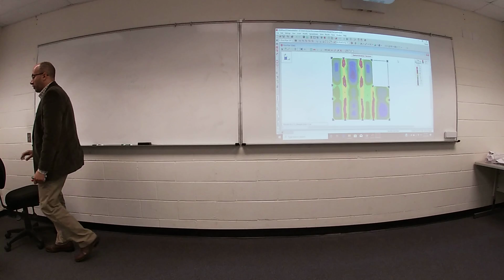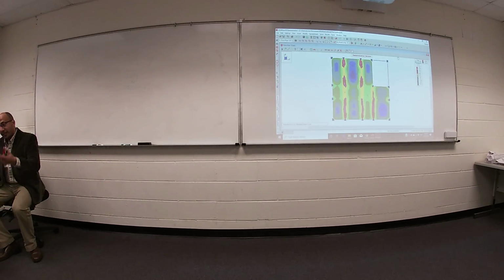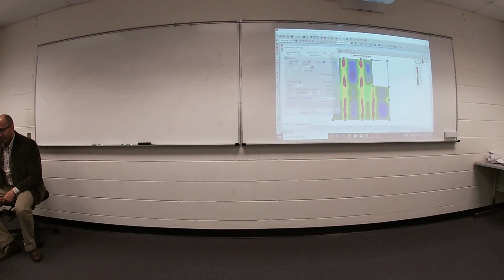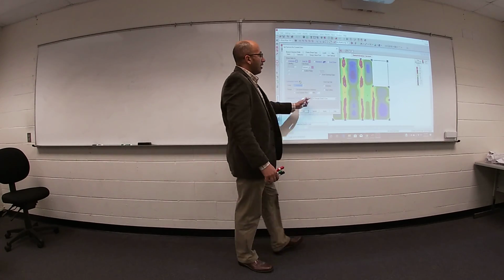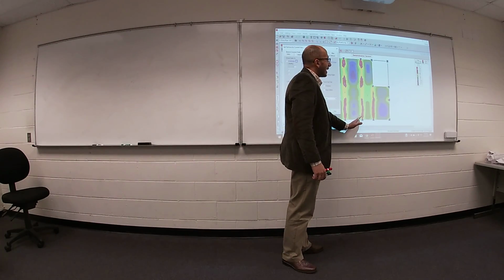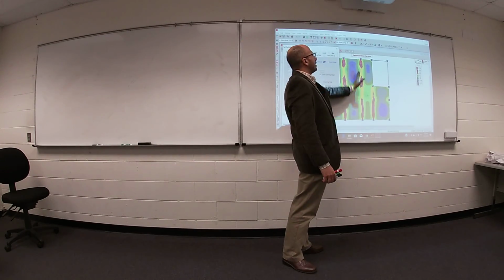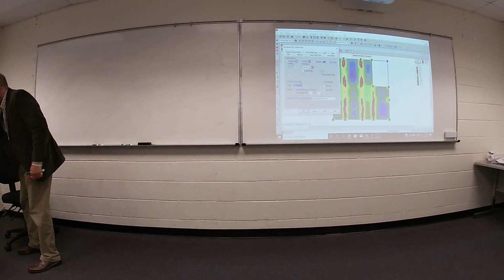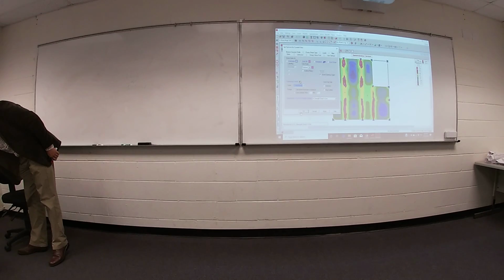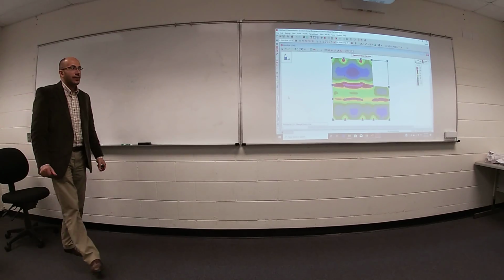If you would like to show another thing, we are looking for Mx. Mx will show you the bending moment that can give you how much steel reinforcement in this direction. Let me show you. Just hit OK. Here you go.